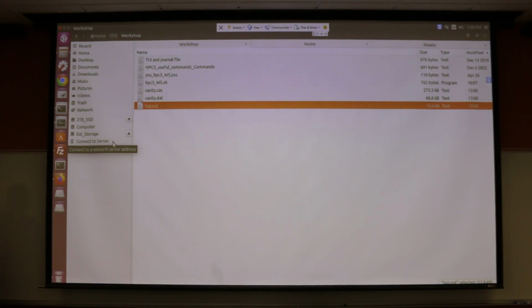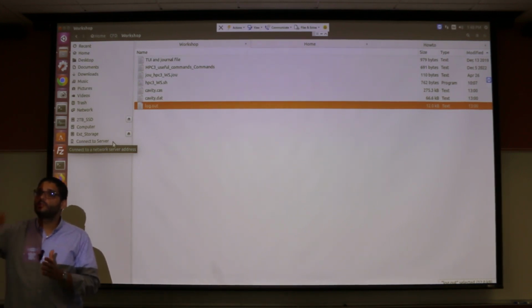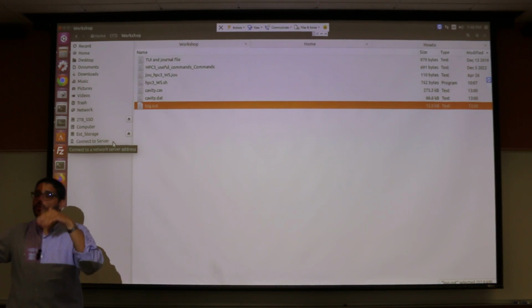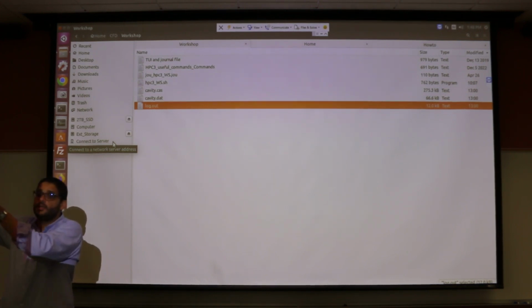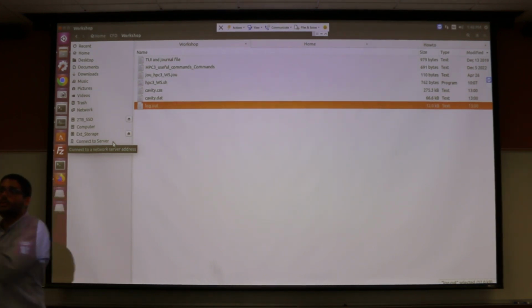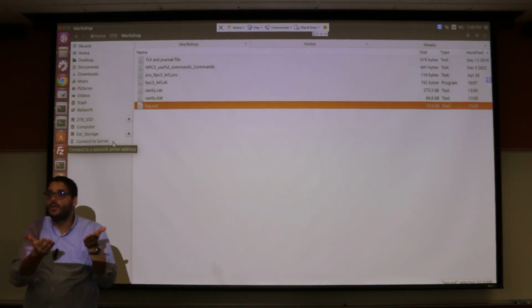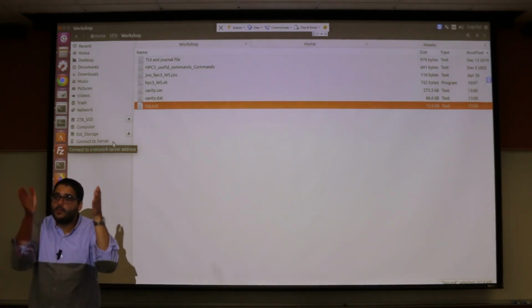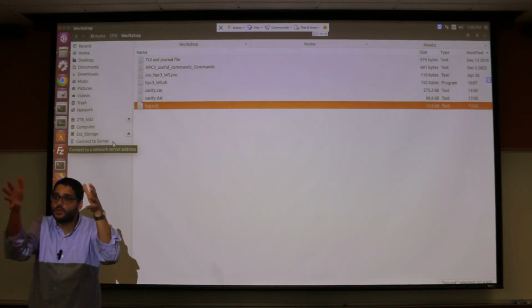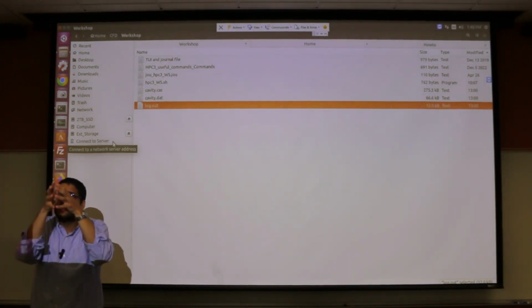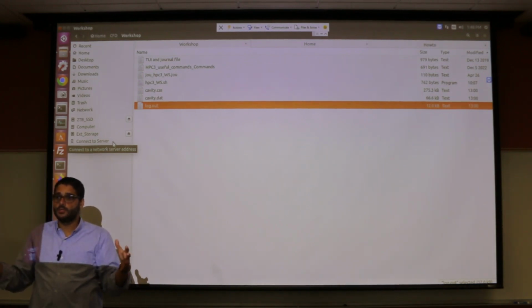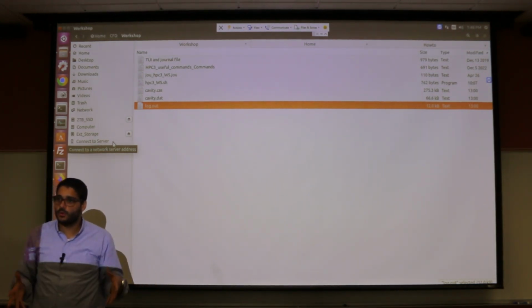This .out is a text file. So what you're trying to say is that if it's a steady case and it reaches convergence, then you are writing the new case with the convergent solution on the HPC. After the job is done, you download your case and data file again to your local PC, and now the new case and data files that you downloaded have the convergent solution and all the number of iterations. You can post-process them on your local PC.